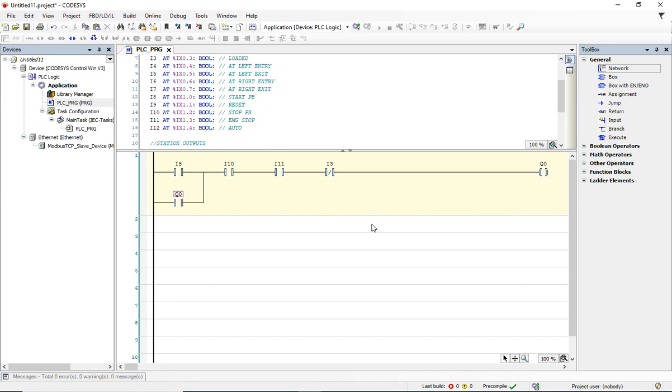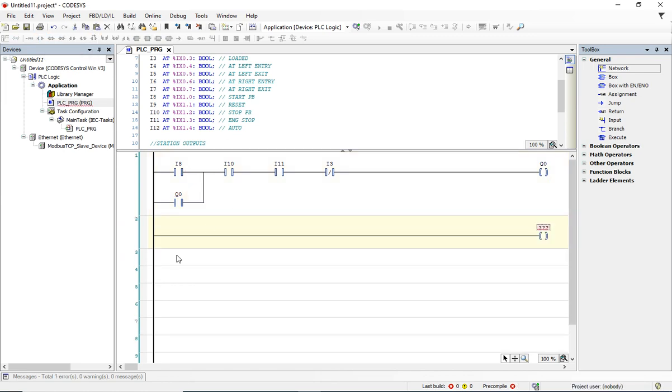And then we want the one at the pallet sensor I2, and obviously you need to put your stop button and your emergency, and the input that is I3, where both of these things must stop.